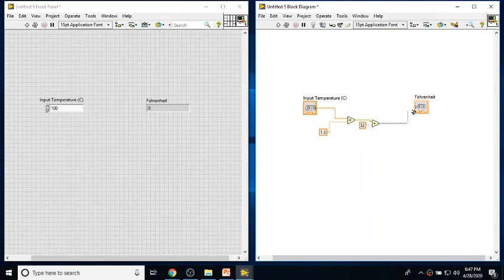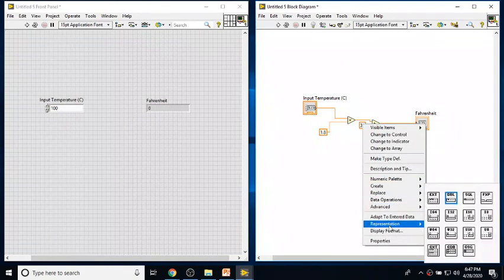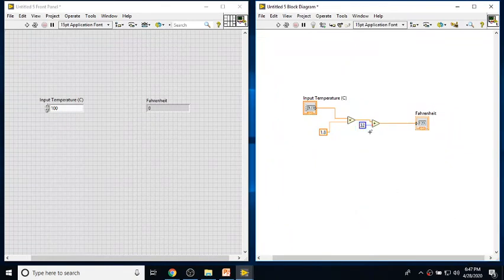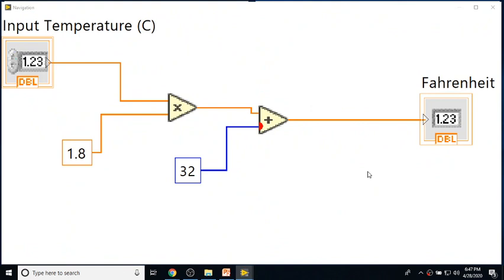So from here, I can connect it from here to here, right? Maybe people may come up with a question, a 32 can be an integer. Why are you making it in orange color, right? So what you're trying to say is this representation, I'll right click on this representation. I can make it I32. You might think this can be like this. Why are you making this to be orange color? The reason is you can see that the connecting terminal point for this add function can have a red color dot when you try to connect in that fashion.